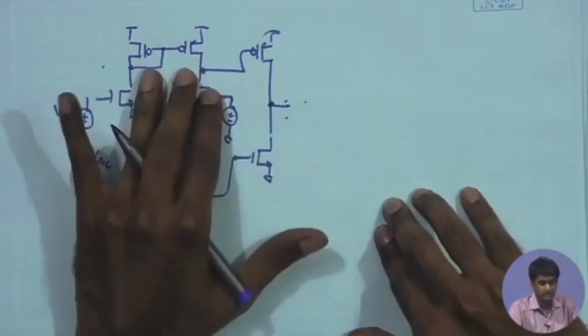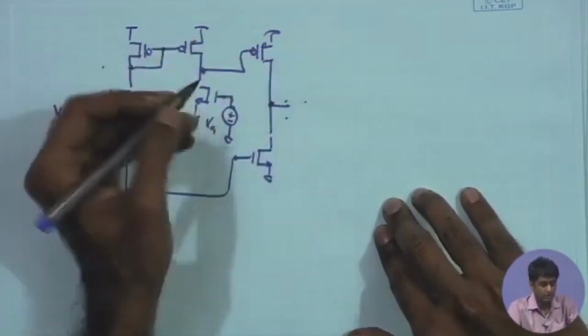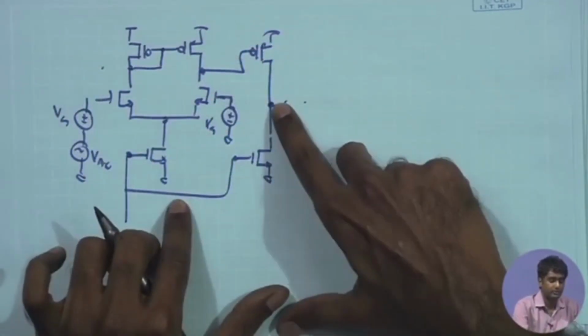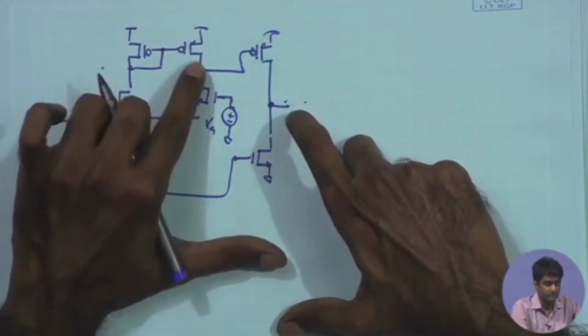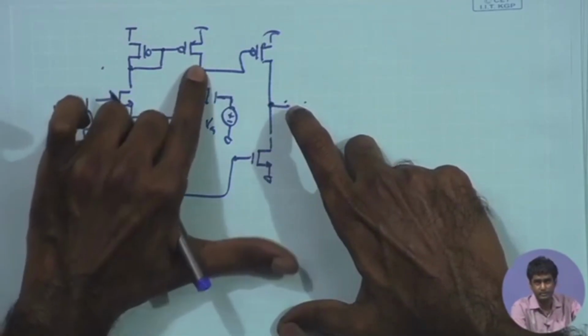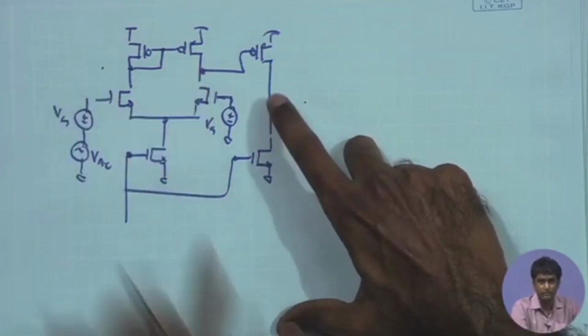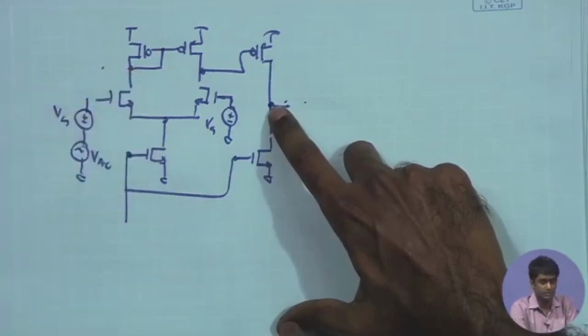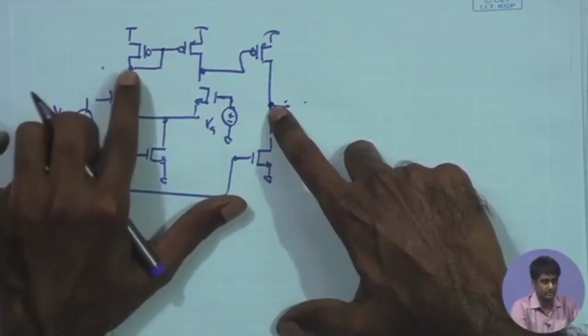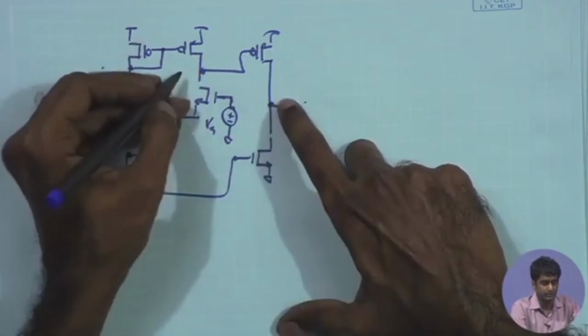Now, if the gain bandwidth product is too large, we know that ultimately bandwidth will be determined by the small signal resistances and capacitances at the output nodes. This is the high frequency node, which is going to give you a critical pole. Another one over here is also going to give you a critical pole. This is a relatively low impedance node that does not give you a significant pole; the pole over here is at a much higher frequency. So these are the critical poles.